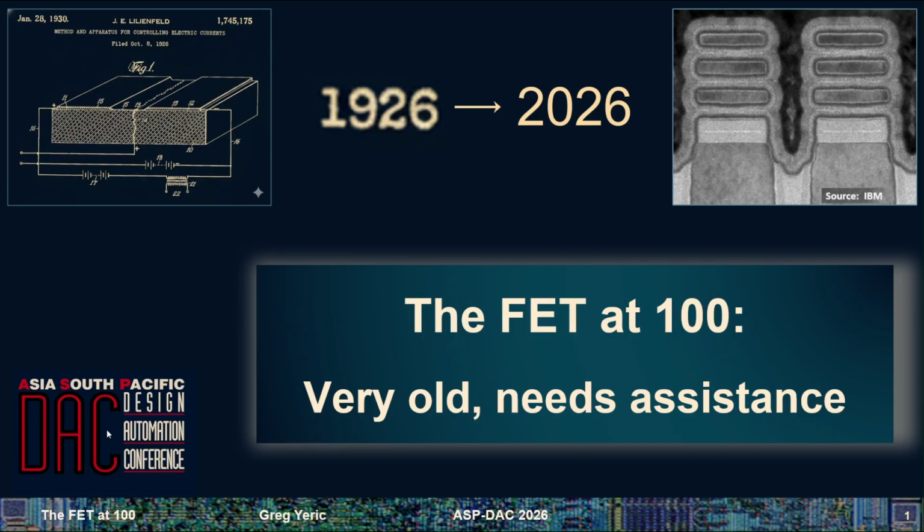So that's the software we use to design chips. And there's stacks of a wide variety of software tools we need for various reasons. Down at the transistor level, you've got SPICE. What is that? Simulation Program with Integrated Circuit Emphasis. That's back from, I believe, the 1960s or 70s. But that is where you model a transistor with parameters that you can kind of understand, like the mobility and the gate oxide thickness.